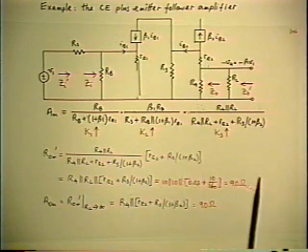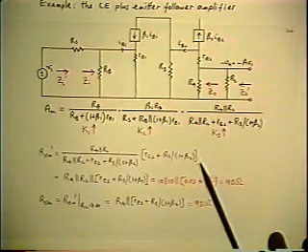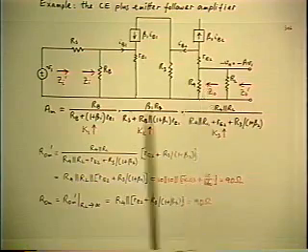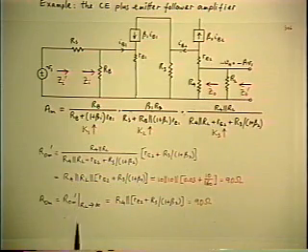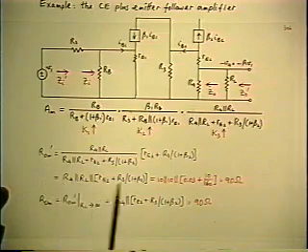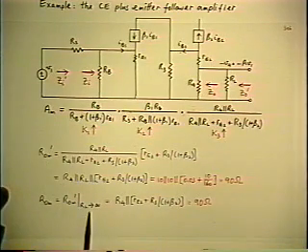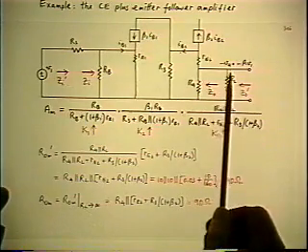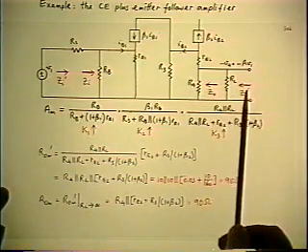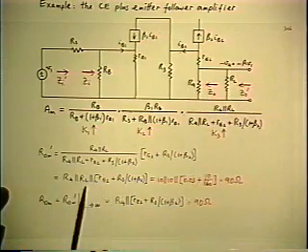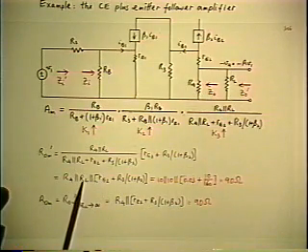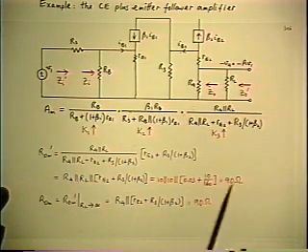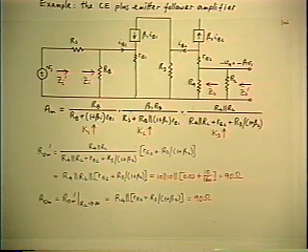Okay, to continue with the application of the theorem, suppose you want the inside output impedance. That means taking the other limit in the answer we got already. So we take the outside output impedance we just found, and you let RL go to infinity this time, which is obvious from the model. If you let RL go to infinity, it simply transforms one impedance into the other, which in this case, of course, simply takes away the paralleling effect of the RL.